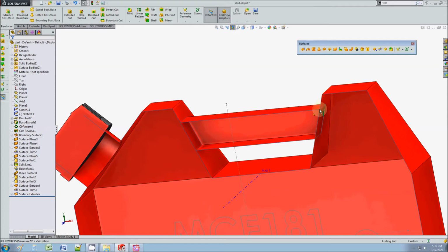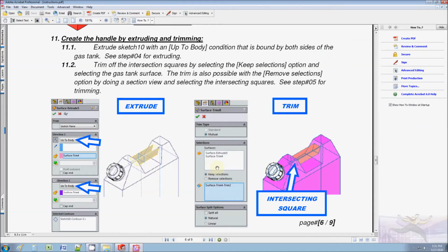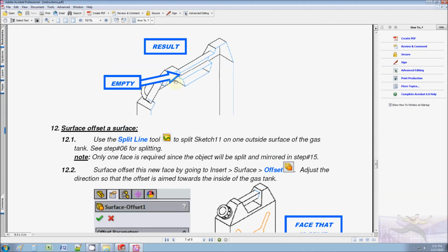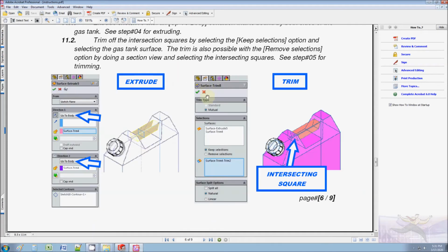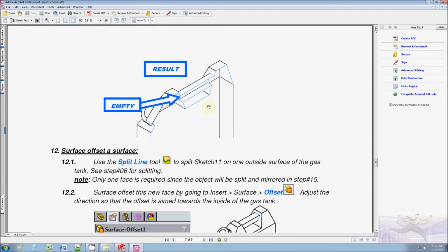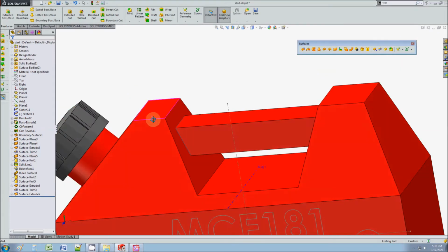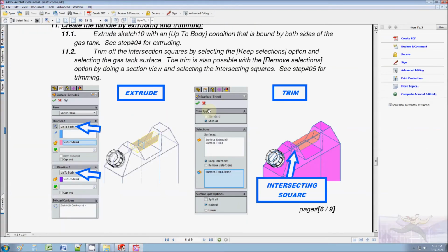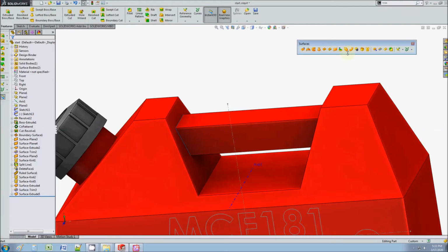If you want this knit to be successful, it has to be a very clean, hollow shell. Just like you see here. See how it's hollow? That's what we've got to do. You're going to come across that issue on the airplane for your homework. On the airplane, the only way you're going to be able to knit those wings is if you create a hollow shell like this. So this is what we're going to try to do now. Alright, so we're going to do this by following this step here. We're going to turn on the trim tool.